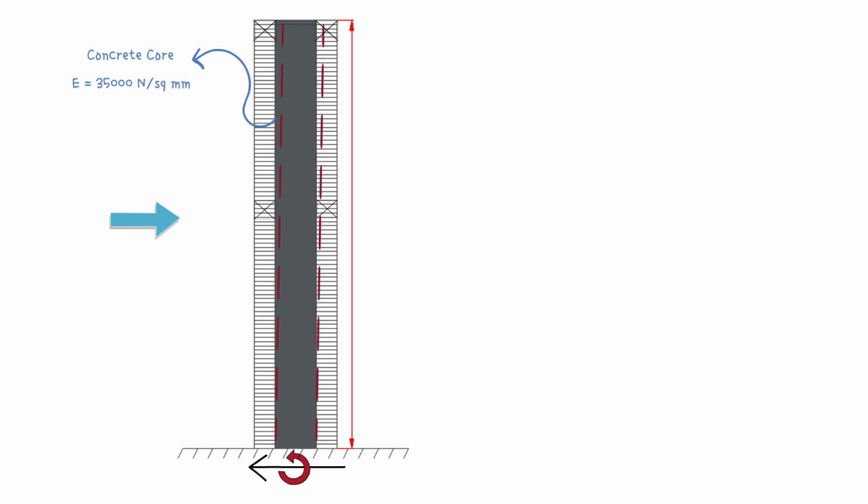Finally, if the maximum allowable wind-induced sway is height over 500, we will determine whether the building satisfies the serviceability limit state condition for sideways movement.